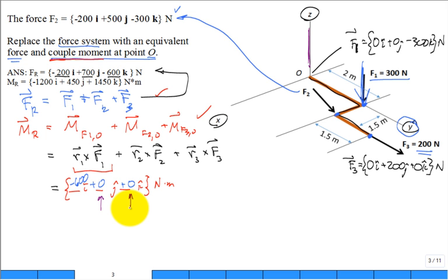But the last one, it's around the x-axis. Okay. If I look at it, I use my right-hand rule, and I say, okay, it's going to have to rotate around that x-axis, and the only way I can make it work is if my thumb points in the negative x direction, and my fingers then curl on my right hand in the correct way to make it want to rotate that way, which, if you're looking from the positive x backwards, is the clockwise or the negative direction.